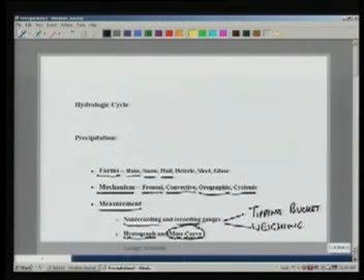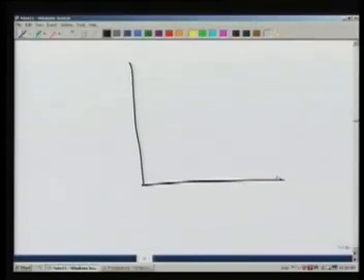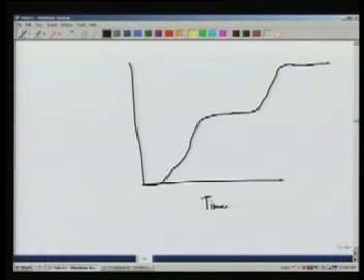In the weighing bucket, as the rain falls on the bucket or on the rain gauge, it gets collected and a signal is sent immediately to record how the weight is increasing with time. So what we get is a directly mass curve of rain which would look like this. Again, this is depth, maybe millimeters or centimeters, time may be in hours or days.